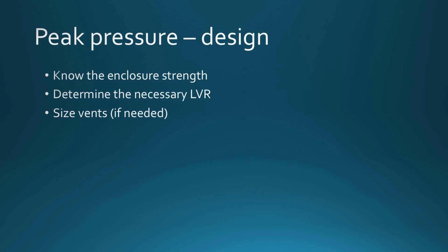For example, if you were to take a room that was 14 foot high, put a 10-foot suspended ceiling in it, and then put the equipment at 9 feet, we would need a vent. If we got rid of the suspended ceiling and discharged agent in the room, we probably wouldn't need a vent. We'd have a hold time that would be 4 or 5 times longer, and we'd have better protection because we've got more agent there.